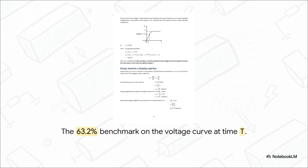But because that pushback we talked about slows it down, by the time we hit t on the x-axis, the curve has only made it to that 0.632 mark on the y-axis. It gives us this highly predictable benchmark for designing circuits that absolutely rely on precise timing.